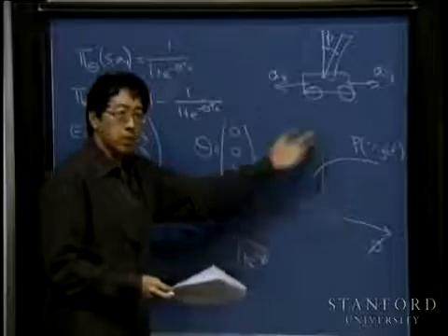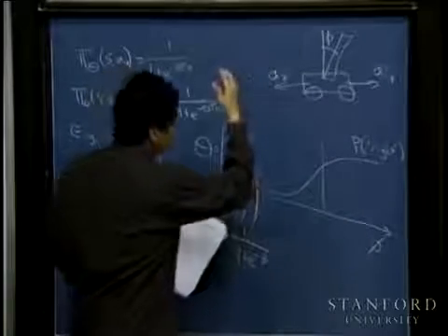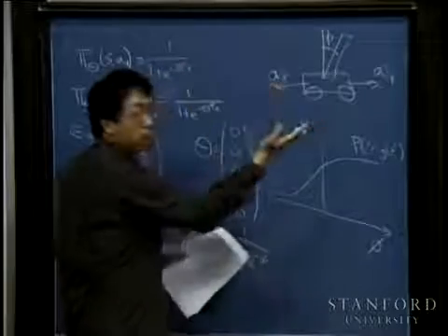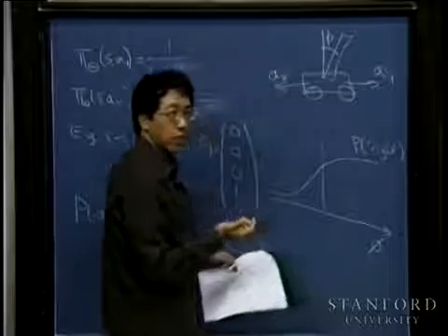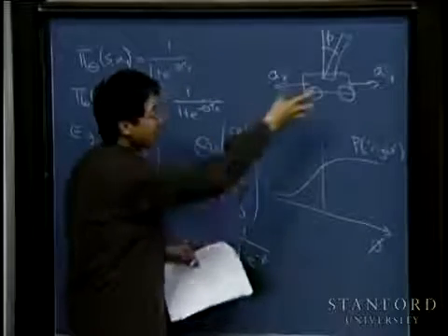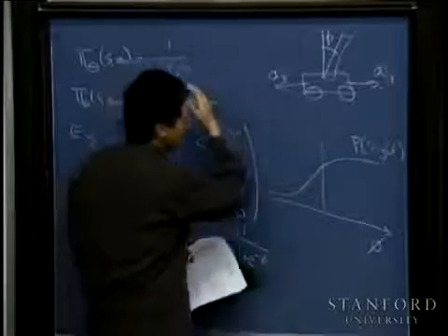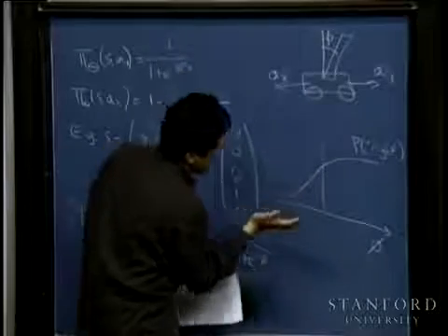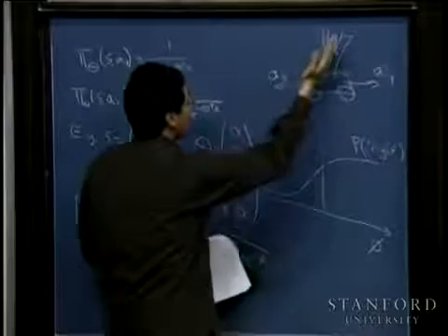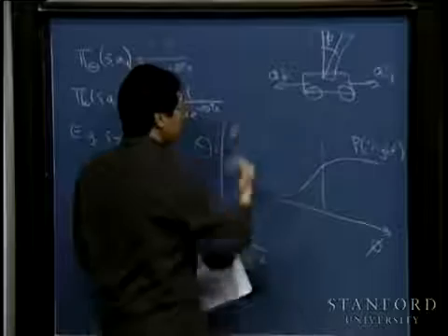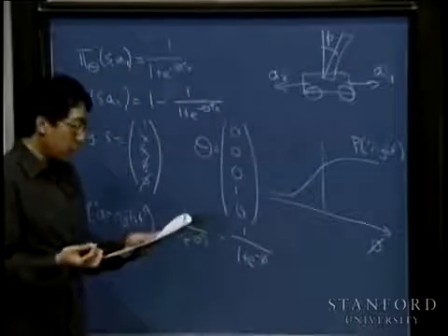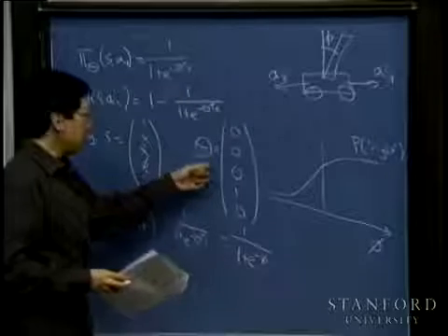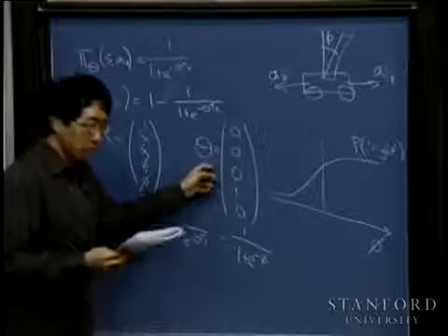So, for example, if my inverted pendulum is leaning far over to the right, then I'm very likely to accelerate to the right to try to catch it. I hope the physics makes sense: if my pole's leaning over to the right, then I want to accelerate to the right to catch it. Conversely, if phi is negative, leaning over to the left, then I accelerate to the left to try to catch it. This is just one example, for one specific choice of parameters theta.